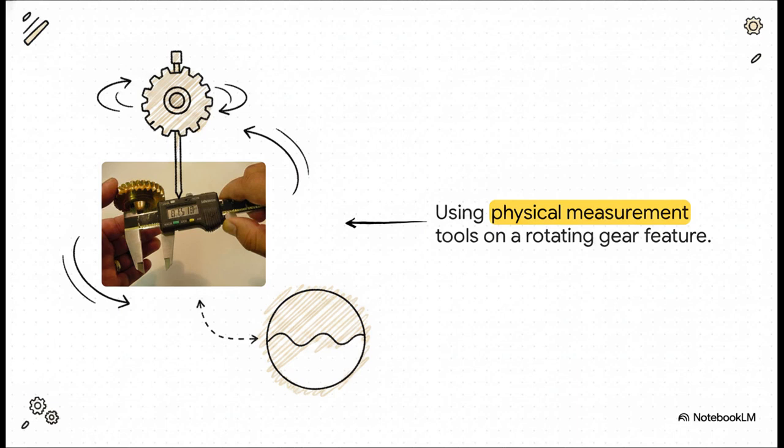While static measurements, like, say, using digital calipers to check a dimension, tell you if a part is the right size, a true runout inspection relies on physical verification using rotary equipment to confirm its actual rotational intent. You lock that central bore onto a precision spindle, drop your dial indicator onto the outer surface, and spin it. This dynamic setup guarantees that the actual manufacturing outcome strictly matches the functional dynamic intent of the component when it finally goes into a live machine.